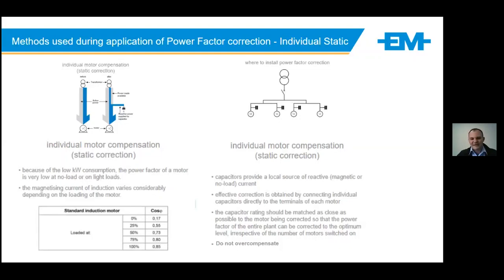In that case, that energy is transferred into the capacitor if it is not disconnected from the circuit. What happens then? It will cause what we call over-excitation on the motor. So how do you prevent that? When the power drops out to the motor, ensure you step out the capacitor at that point in time.